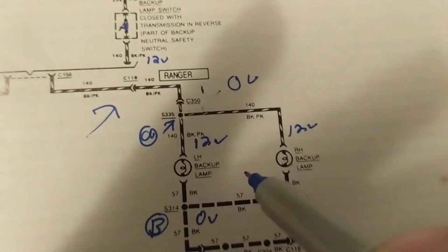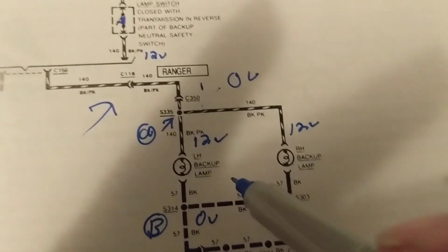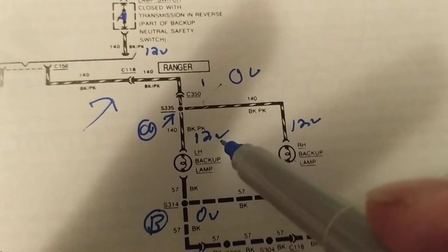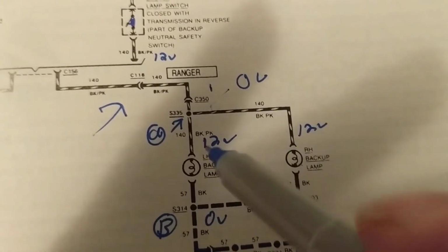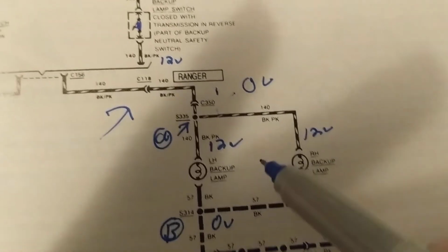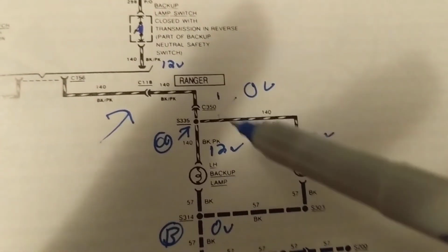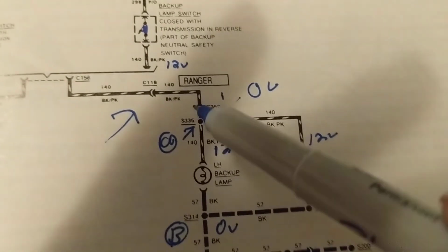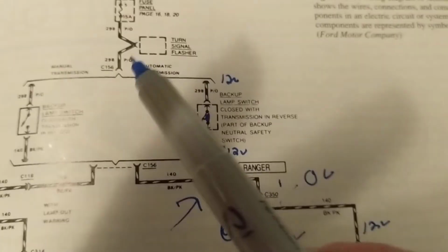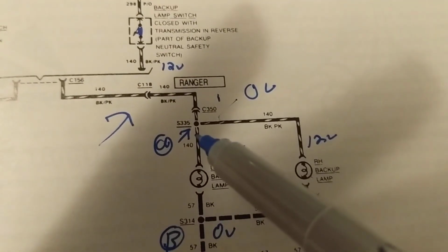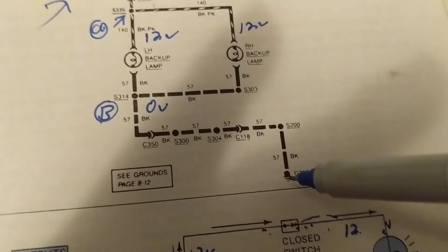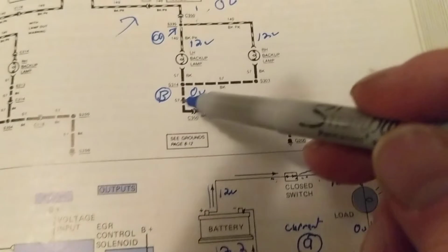So therefore, if they are both out, how do I know? Well, I go and put it in reverse, and I usually look at the reflection of the car in back of me, and I see a reflection of 2 lights. I know both are working. So if both are not illuminated, I come to the conclusion it's either the switch, the fuse, or this wire, not these wires, or a ground could be open also. So therefore, A over here I put to signify this point. B I put over here to signify this point. Go over it.